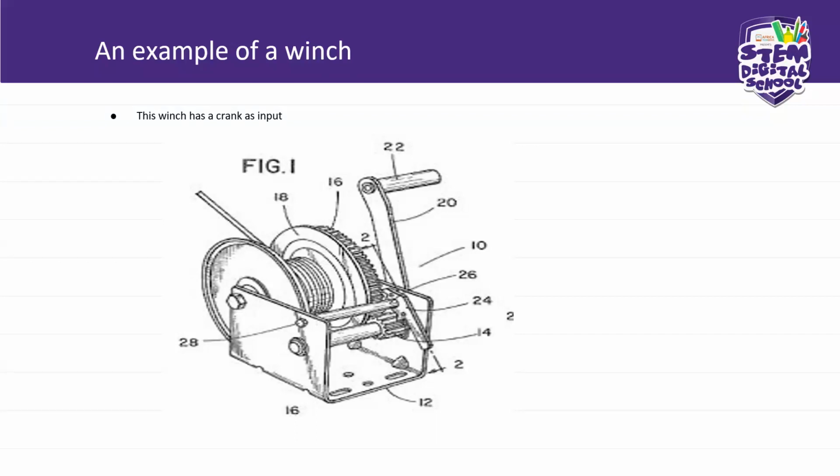Even in hydraulics and pneumatics, you will see that where the size of the input is small, the input force is multiplied in the area of the output. Just put that in your mind and you will know that that is how we acquire mechanical advantage. The area of the input and the area of the output becomes very important when it comes to mechanical advantage. Input force is multiplied in the output if the area of the output is bigger.